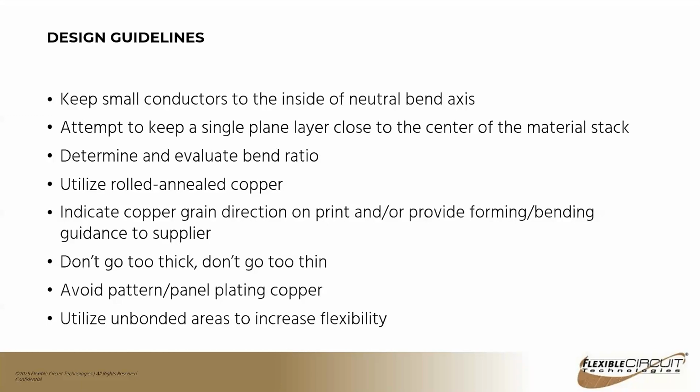Avoid pattern plating copper. When you have a double-sided or higher layer count part, do pads-only plating so as not to deposit any additional thickness, any additional copper. Electroplated copper is not as ductile as just the rolled annealed copper, so eliminating that from your flex can be important. And then utilize unbonded areas to increase flexibility, which we're about to jump into on the next slide.